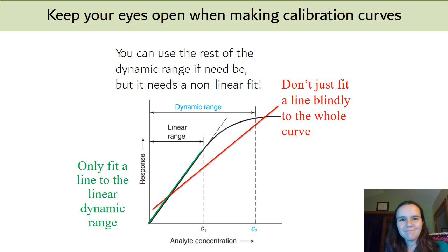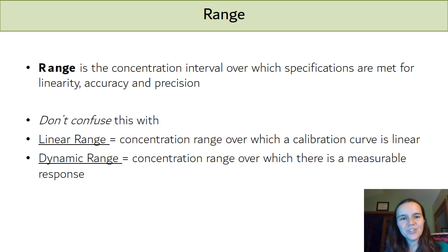And so just be careful, as long as the response continues to increase. So you do get an increase from here up to there. Let's see, sorry, it's not really level. So that part is still dynamic, it's just not linear dynamic. So if you have to use it, make sure you're not doing a linear fit. Which leads us to range.